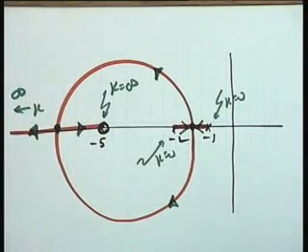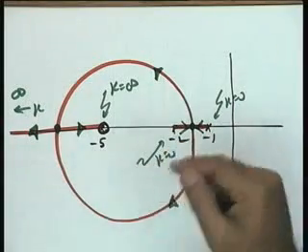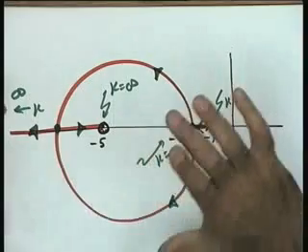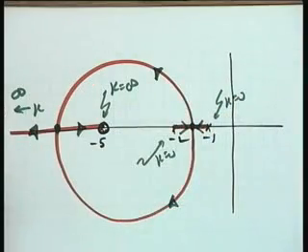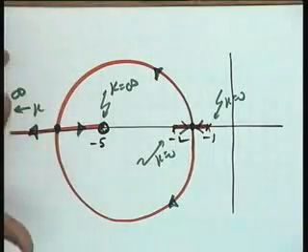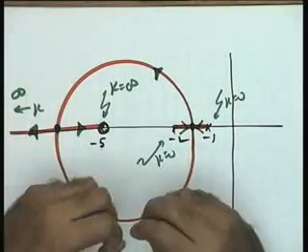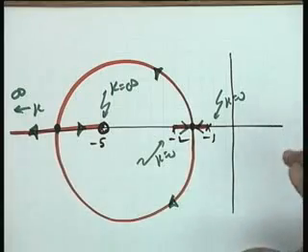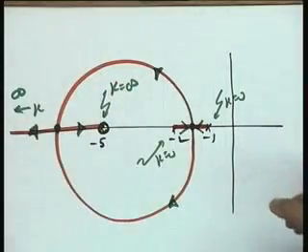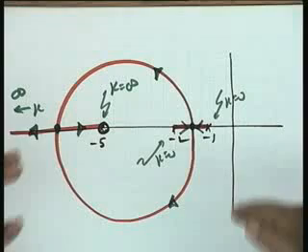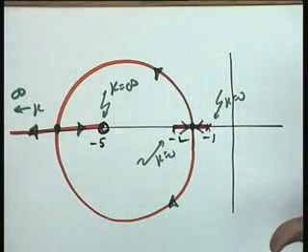Without the 0, you recall the root locus diagram, it was a vertical line. When you added an integrator, the vertical line was pulled towards the imaginary axis. So it means the integrator was making the system less stable. And when you have added a 0 into the system, say a PD controller, the vertical line has been pulled towards the left hand side. It means the system has now become more stable. One observation which we have made.